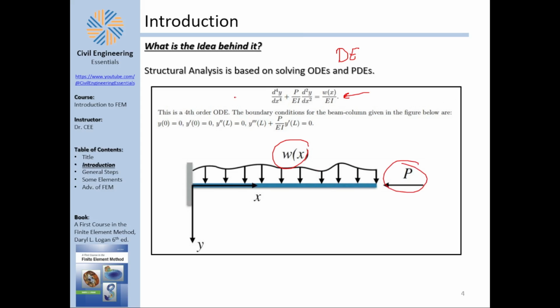And this is no joke to solve. I mean, it looks cute, and maybe you can solve it. But if you go deeper and start talking about planar elements, this becomes really hard to solve. Also, this is just one beam. What if I add another column here with a fixed support, for example? How would you solve that now? Because suddenly your change in y, which is deflection, with respect to x is not only related to this element, but related to this element too. It becomes really hard to formulate problems like that.